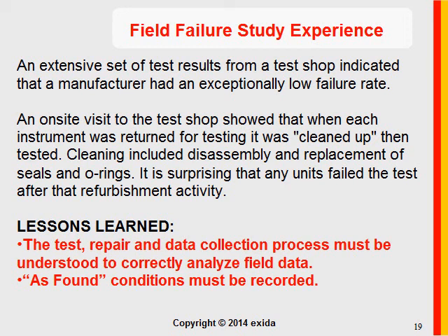So lessons learned: the test, repair, and data collection process must be understood to correctly analyze field failure data. If we don't understand how that testing and repair process goes while we are evaluating the data, then we may come to the wrong conclusions. And in this case, as found conditions were not recorded, so key problems were potentially already removed before the unit was tested.